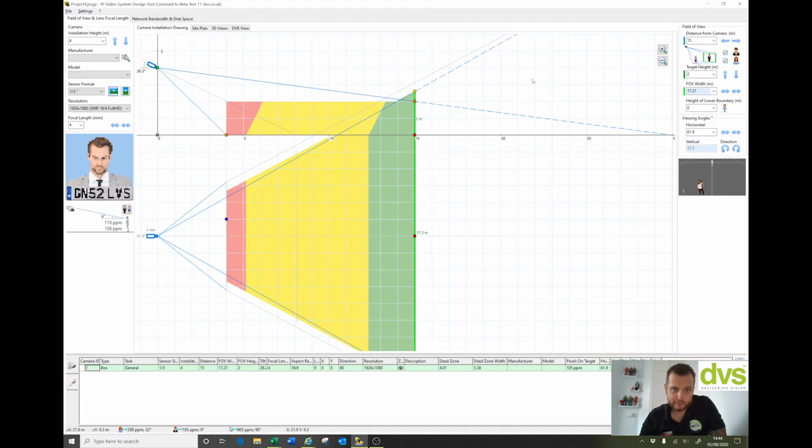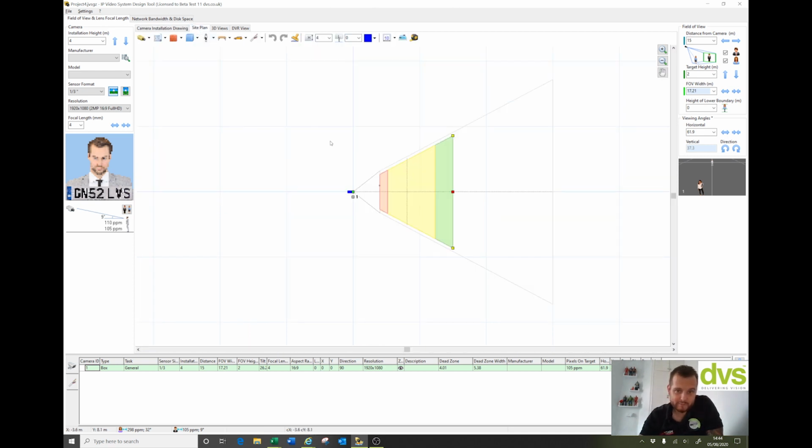Okay, so once you open the software, the first thing you need to do is upload the site plan. Whether it's the internal floor plans, you can put layers in it, you can do them separately and make a PDF, but this is the basic gist of it. So go to site plan, right click in the image and go to load background image, or you can go to load Google Map directly.